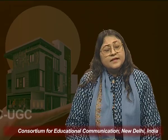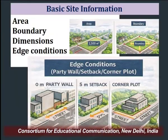Next important factor is the area, boundary, dimension and edge conditions, which are taken again into site information. Area means what is the total plot area. Boundary is the perimeter of the site. The dimensions are the length, width or the angle dimensions, and edge condition means how it is being abutted to the road. So, for edge condition, you have one street facing or you have two street facing, and according to that the setbacks are decided, which have been discussed in the building bylaws lecture.